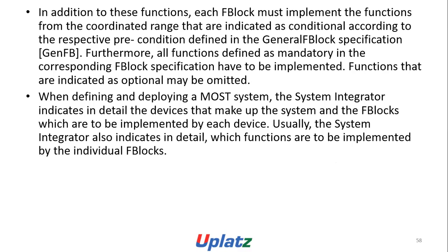In addition to these functions, each FBlock must implement the functions from the coordinated range that are indicated as conditional, according to the respective precondition defined in the general FBlock specification GenFB. Furthermore, all functions defined as mandatory in the corresponding FBlock specification have to be implemented. Functions that are indicated as optional may be omitted. When defining and deploying a MOST system, the system integrator indicates in detail the devices that make up the system and the FBlocks which are to be implemented by each device. Usually, the system integrator also indicates in detail which functions are to be implemented by the individual FBlocks.